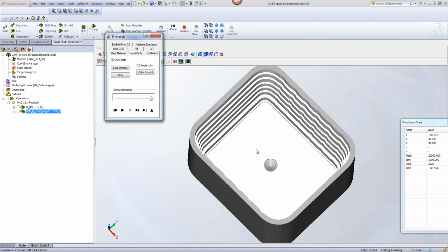end mills that cannot cut at the bottom of the end mill itself. So they need some kind of a lead hole. So in this particular case, if they have that kind of an end mill, in these areas over here, it cannot go in by the way we normally go in an HSM, so therefore it did not work in those areas. This is why I created the two holes instead.